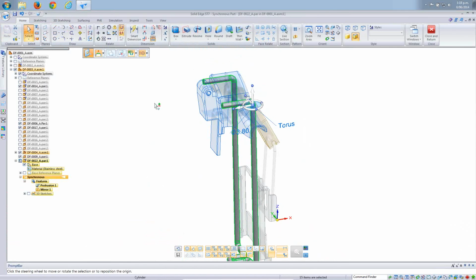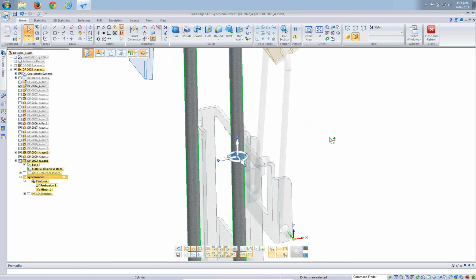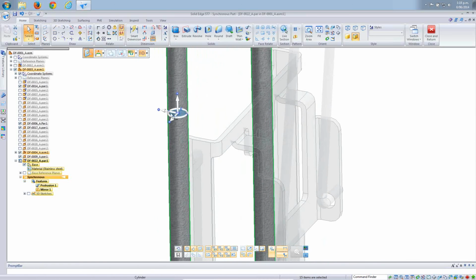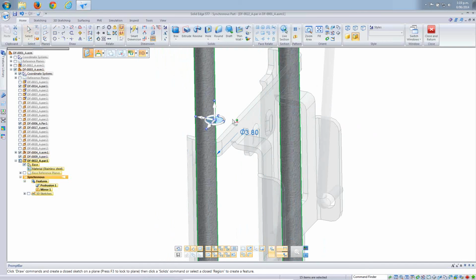I'll pick up a couple of the extra cylindrical surfaces. Steering wheel manipulation. I'm just going to move this down a wee bit. It's still snapped to the center of that cylinder. The long piece on this new component, and I do need to offset it as well, so I can offset the steering wheel. I'd really like it to sit on the outside cylindrical face here, so 3.8 divided by 2. I can work it out as 1.9, but just to show you can add in little equations to those input boxes. We'll then move the whole model so it's seated on the inside face of this guide component.